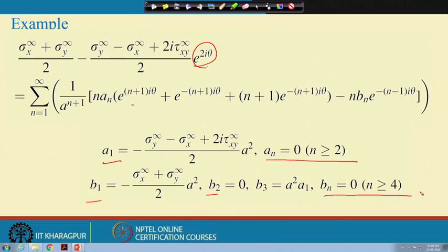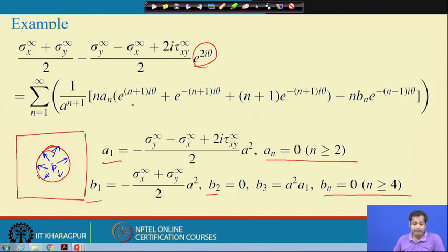But remember, if the problem is slightly different, in the sense that this is the hole, but suppose this hole is not a stress free hole, so you have some forces, some pressure P here. Then you may not get this equation, because you arrived at this equation by substituting that boundary condition.